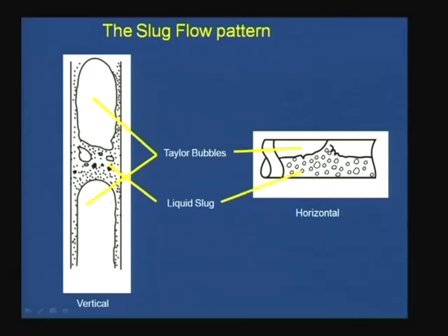So, therefore, what we will do? We will be primarily discussing slug flow in vertical pipes, because slug flow is more commonly encountered in vertical pipes, and after we have finished discussing, we will take a brief discussion on horizontal slug flow as well. Remember, whatever we have discussed for vertical slug flow cannot be directly applied to the horizontal case. Yes, it can be applied where? Under micro channels. Why? Because the moment we go to lower and lower dimensions, surface properties become more important and gravitational force gets a back seat.